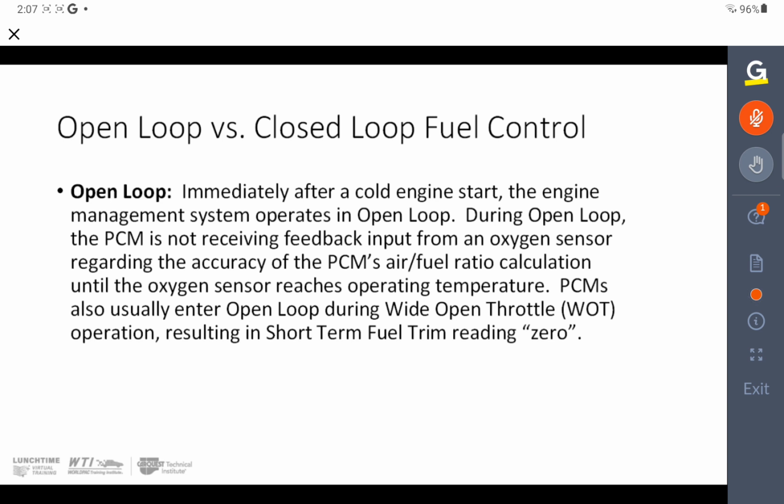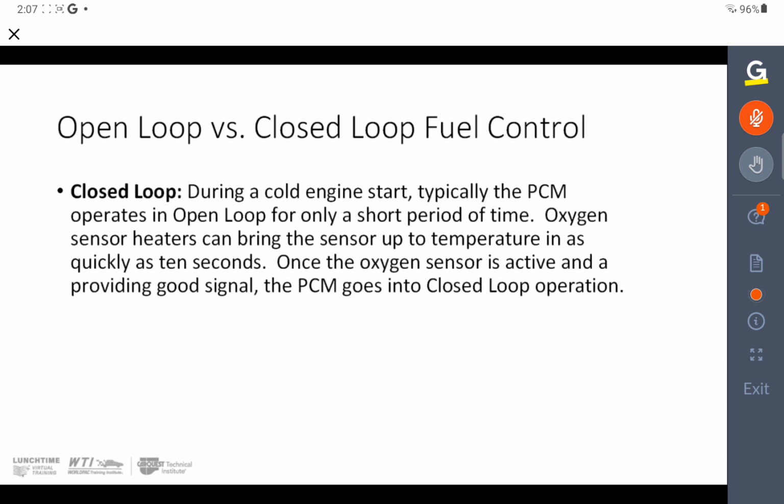Typically when it's at wide open throttle, we're going to see a short-term fuel trim reading of 0. I have seen on some cars where if it idles for too long, it will go into open loop and the fuel trim will show 0 for short term.